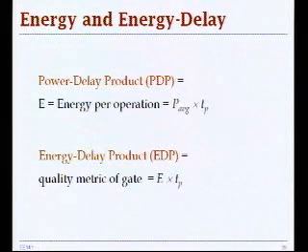So the speed of your circuit and power consumption are really related, because the propagation delay is actually the speed at which you can charge a certain amount of energy into your gate capacitance. And the faster you go, the more power you dissipate. The product of the two, power delay product, is normally constant for a given gate and a given topology.